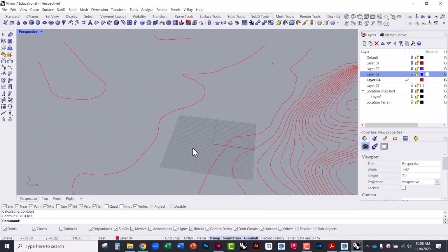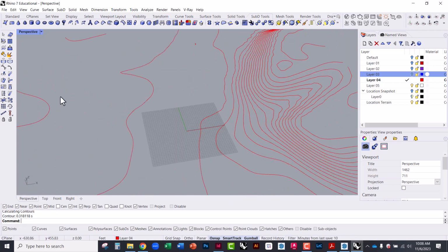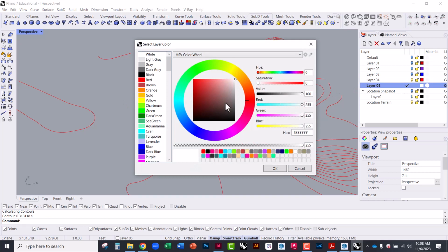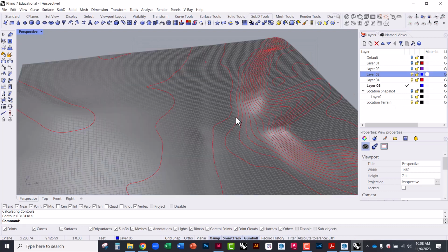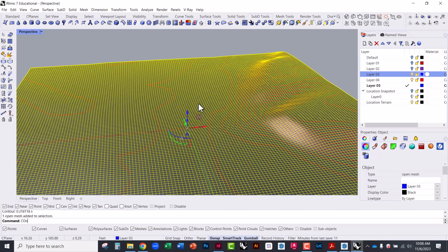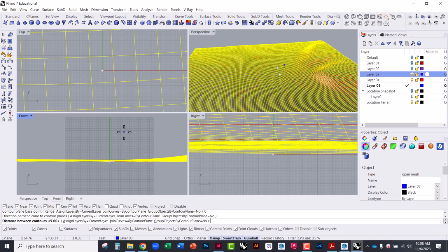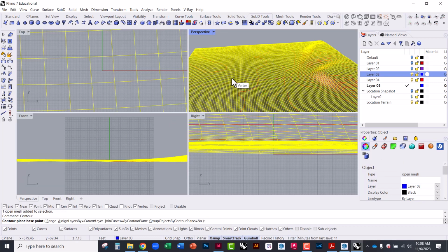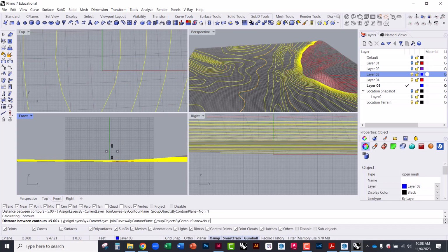And obviously with this, we're not getting the individual contours between these. So, you know, maybe this distance is good here, but we're not really seeing much change here. So I'll create a new set of contours. We'll make these blue, and turning this layer back on, select this contour, 0, up, and I'm going to set the distance to 1, so 1 foot.